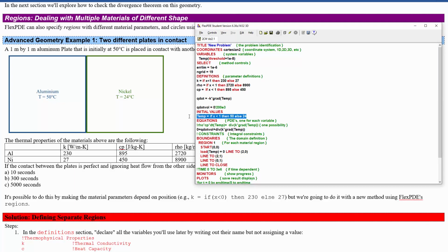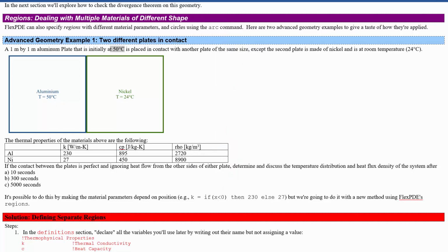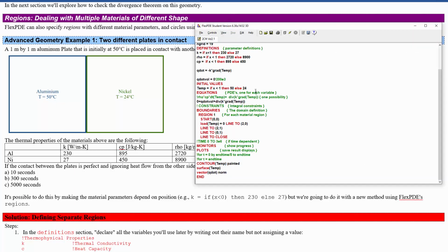If we don't start off with a time-dependent simulation here, then there's nowhere that anything except the conductivity makes it into the equation. So this isn't saying it really started at this temperature range. It's not actually applying the initial conditions. That's just saying what's the first guess to use for the steady state temperature, which could be anything if we don't model the time involved. Okay.